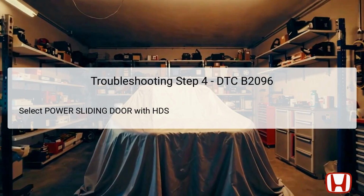In the fourth troubleshooting step, the technician should select power sliding door using the HDS and enter the data list. This action allows for a detailed evaluation of the current operational status of the power sliding door mechanism. The data list provides real-time information on various parameters, including the status of the B-pillar open and close switches. This is crucial for identifying whether the system is receiving accurate input from the relevant switches.